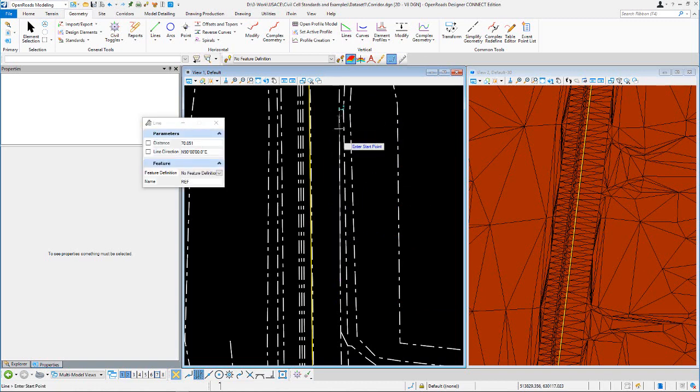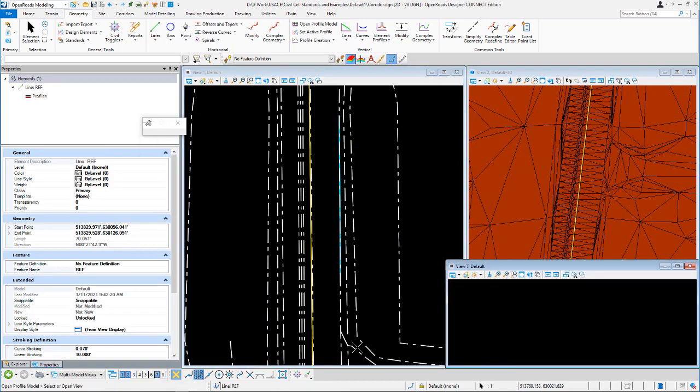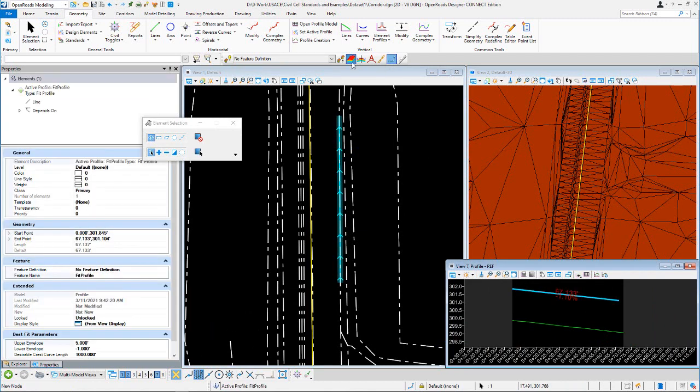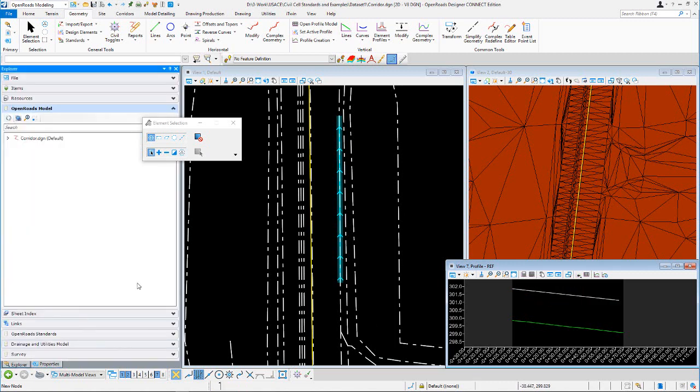You can say it's about a 70-foot line. It's probably more than I need, but I don't forget what kind of width you need here. So if we'll look at the profile view here of this element. Alright, so that create 3D automatically, which I want to go ahead and turn that off. That's one of those buttons you turn on when you want it. When you're done, make sure you turn it off because it creates 3D automatically. It doesn't matter what you're doing, it's going to try to create 3D automatically.